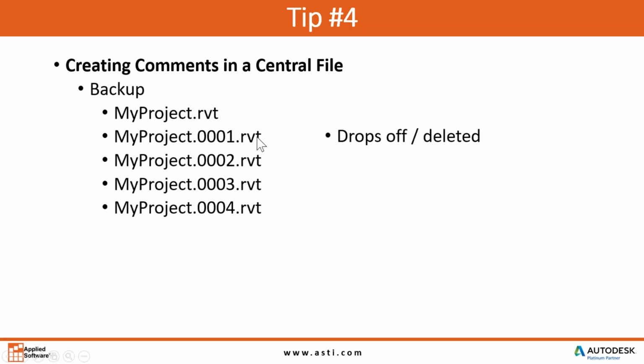Now, what we recommend, what we tell folks is, if you know you've done some major design change or whatever, you may want to consider going to where your project is saved and creating a zip file of that. So maybe the 004 file was super great, and I'm just going to right click and zip or archive it, or maybe even pull it offline to somewhere else, because as I said, if I go to save 5, 6, 7, 8, it's going to eventually get rid of this 004 save I have, but that may have been important. I don't want to lose it.